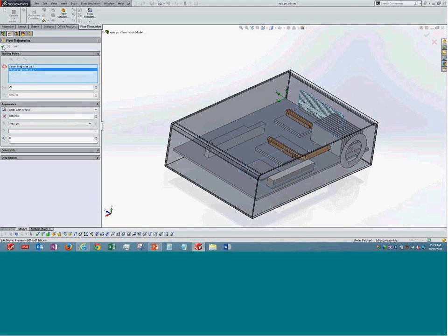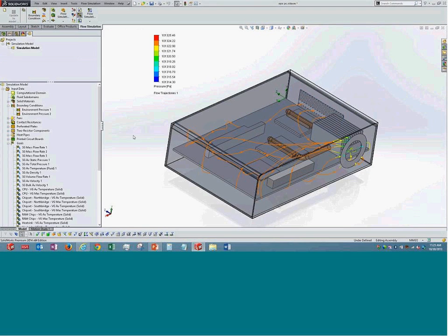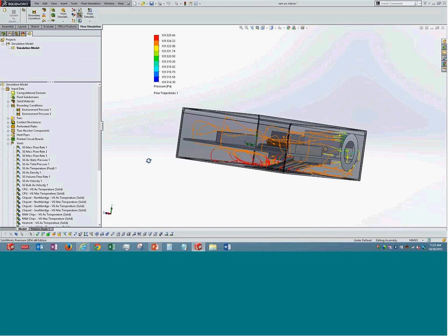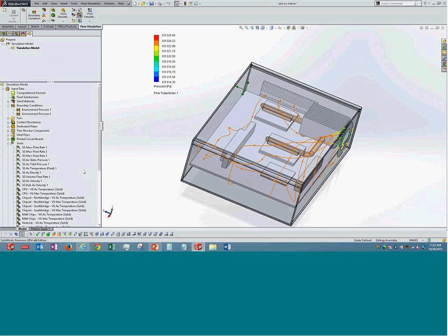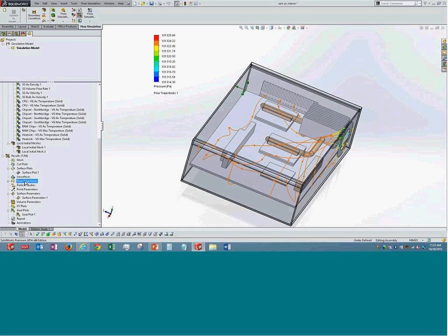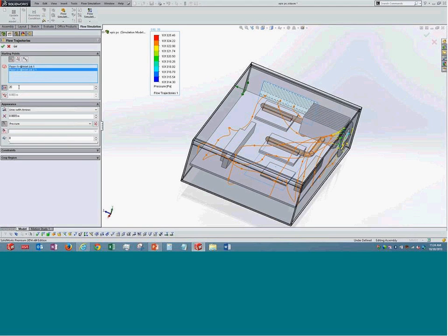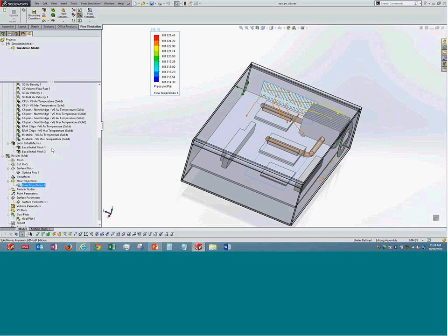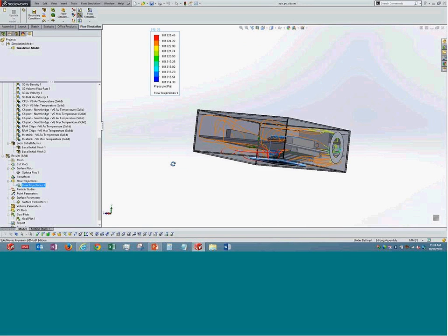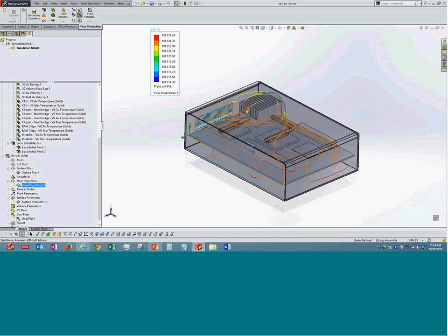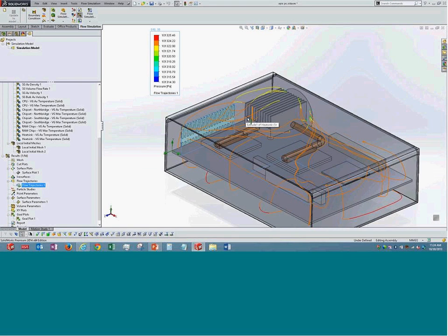Now let me move on to the next module. What I discussed is the model that I showed you, that is heating, ventilation, and air conditioning, with different capabilities. But an interesting part, or one cool thing, is something called a tracer study over here. Now, by the way, this is an external flow analysis. So you see we have selected external. This is all a time-dependent analysis. So that option is selected. There is a single fluid present, and other options are almost the same.